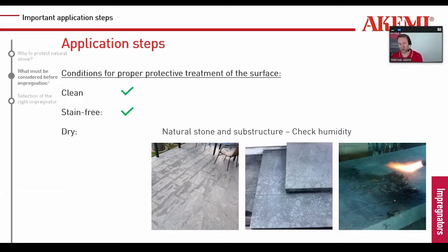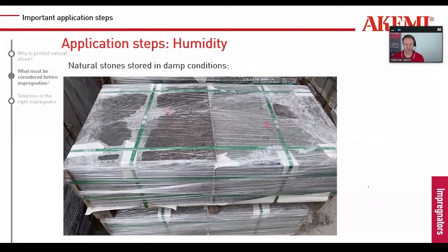First, I will show you another picture, also something like that. When your stone is packed with plastic, you can be sure there is some humidity trapped inside the stone. So here you have to be sure to dry it properly. If it's not warm enough, take a flame and dry the stone, and then you're good to go with an impregnation. Yes, let's do that.